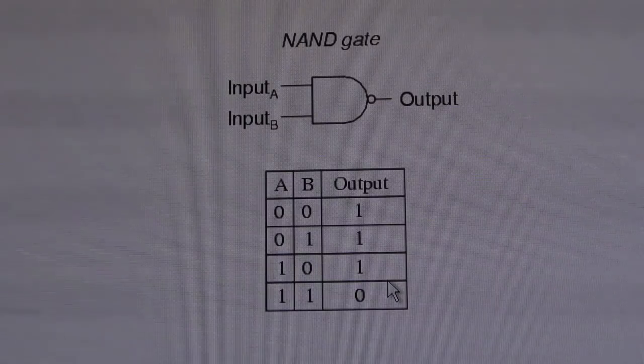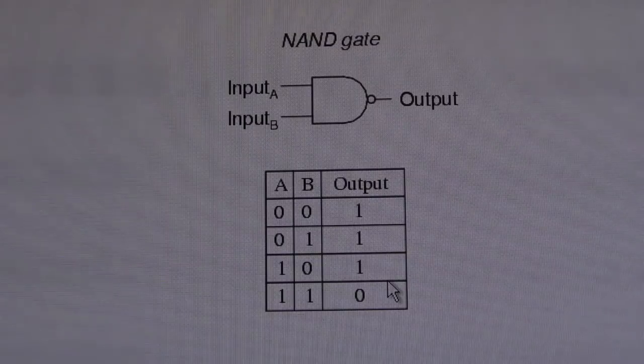The other thing worth mentioning is the 6502, and in particular the 6502 on the NES, the Famicom. It's probably, I think, a CMOS part. It's not TTL. So it was just worth mentioning. Like I say, in general, the principles are the same. It's all about the voltage thresholds and the speed of these devices. But also, the other thing I didn't mention is CMOS is much more sensitive to static, ESD discharge and stuff, whereas TTL is a little bit more hardy in that sense.